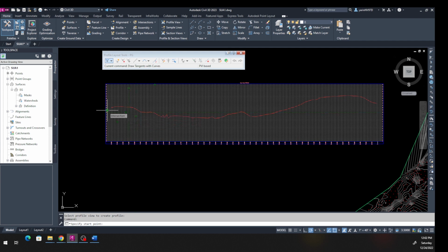You can create a new profile, and that depends a lot on your cut and fill, how much you want to cut out, how much fill you want to bring in, the existing material type and stuff like that. So let's go ahead. You want to start from right here where my cursor is, and this is your new roadway. Remember, you've got to stay within the design criteria.